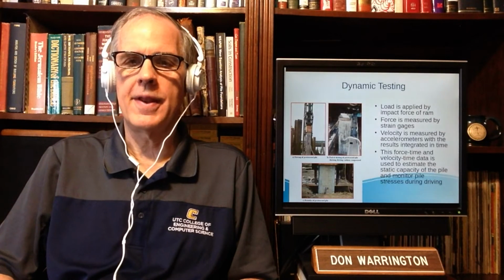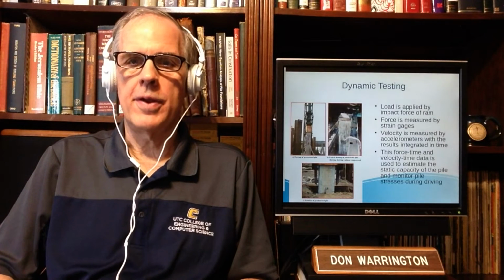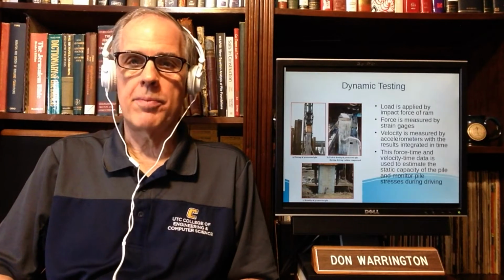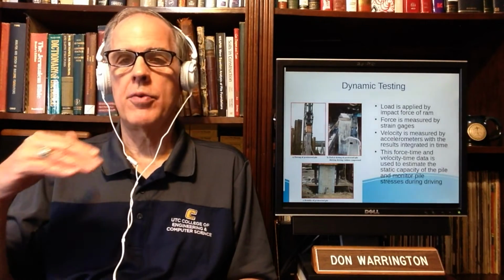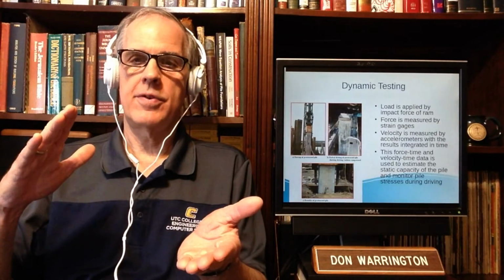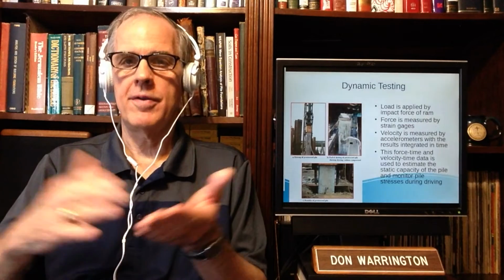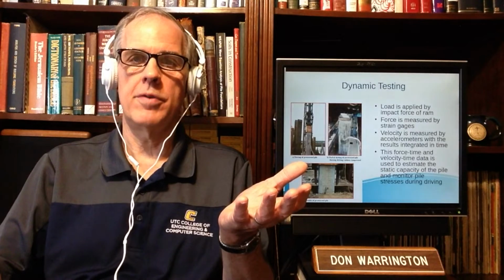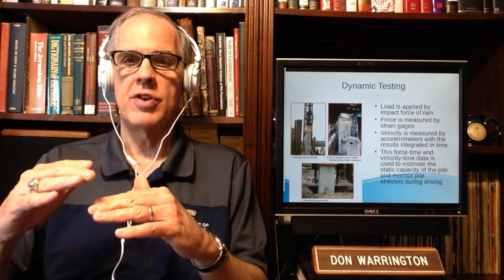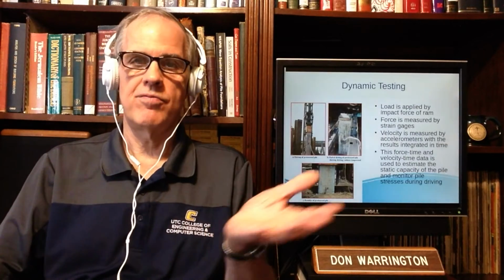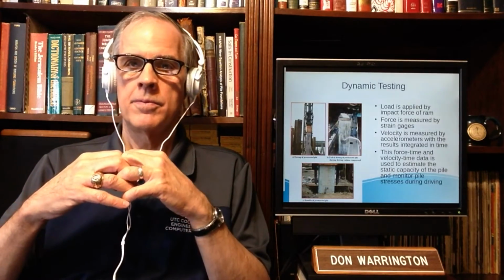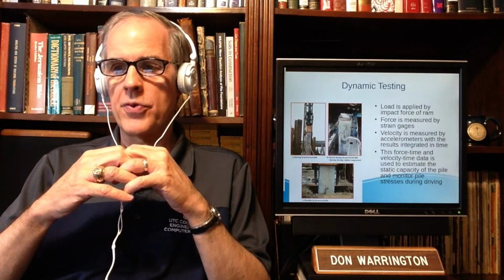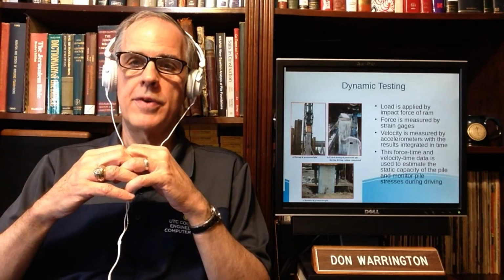I talked about at the beginning of this lecture the rather primitive blow count thing we used to do. We still take blow counts. Usually, if the pile advances a foot, they count the number of blows on it, blows per foot. Set is 1 over blows per foot, or the number of blows in an inch, blows per inch is 1 over that.